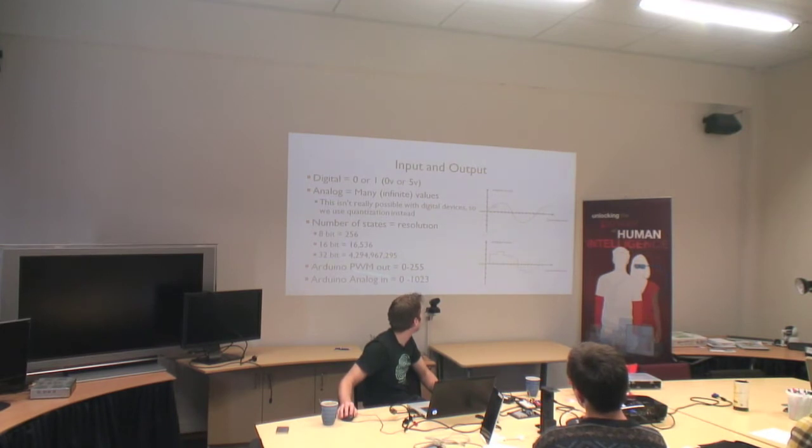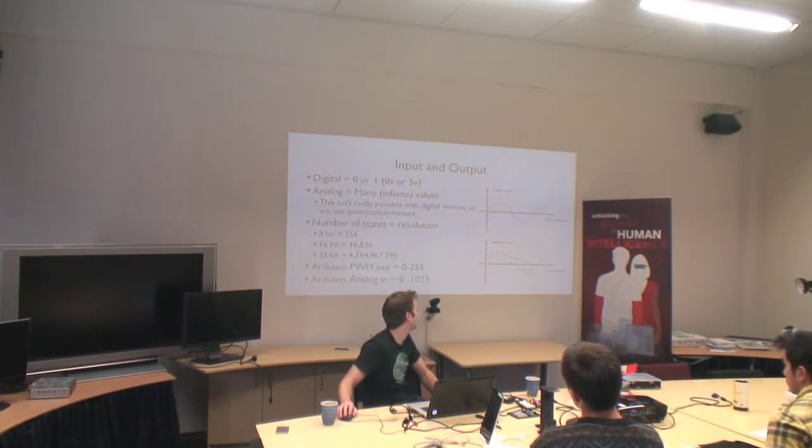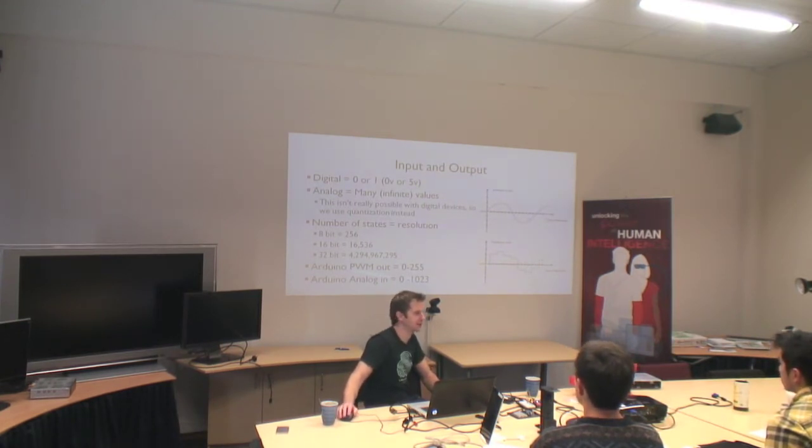But then you go, okay, at this time here it's 2, at this time here it looks like it's pretty close to being a 3, and so on and so forth. So you basically map it in from a nice smooth analog curve to a discrete, blocky, digital curve, but you can sort of approximate this with this, and for most applications, as long as you've got enough values, this will look close enough to this that certainly the electronics won't care.